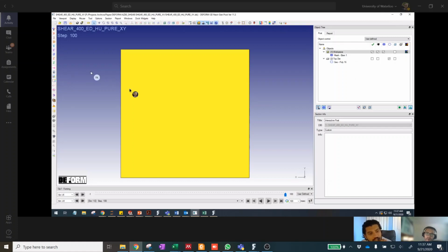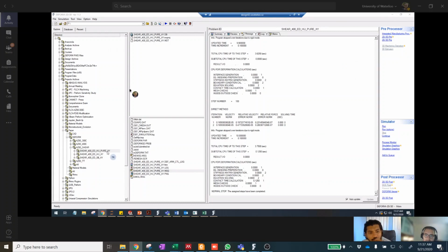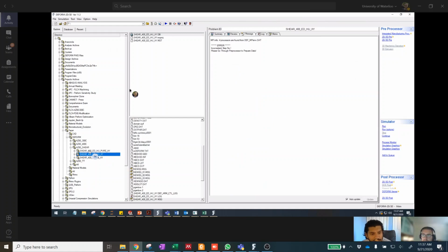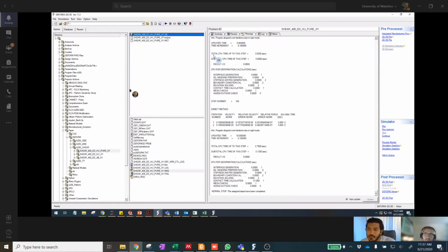But the one where you impose the velocity to the nodes instead, that one was deforming a ton. Can you bring that result back up? We can bring that up and assign the free boundary conditions. I don't think the free boundary conditions fixed it. To be honest, I don't agree that the rotation about Z needs to be free. Just the one that you did, with fixing the one face in the Z direction. Well, I'll have to rerun it because I saved over it. No problem.